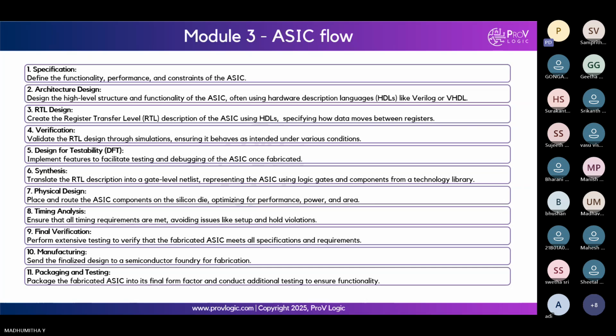Next is architecture design. So now we got the requirements from the client. Next is architecture design. This architecture design will be done by the top level team of our VLSI domain, of whichever company you're going to work. Their top level team will do the architecture of the IC. Architecture of the IC means how many SRAMs must be there, how many ALUs, arithmetic logic units, must be there, how many interface buses must be there, how many input ports, how many output ports, how many power ports. So designing all of this is called architectural design of the IC.